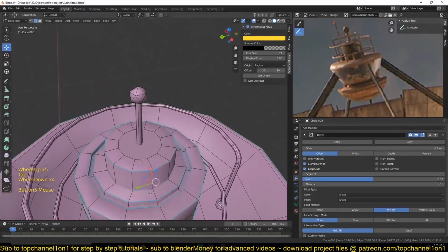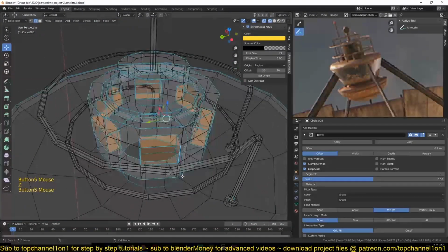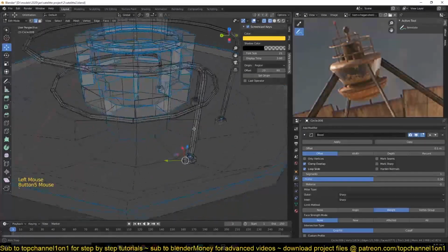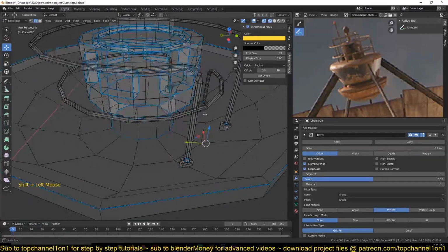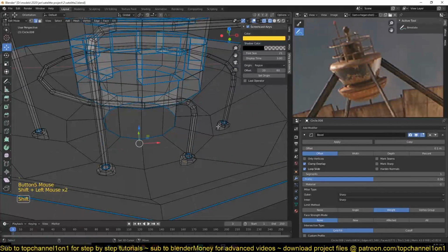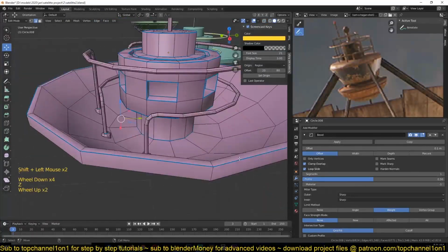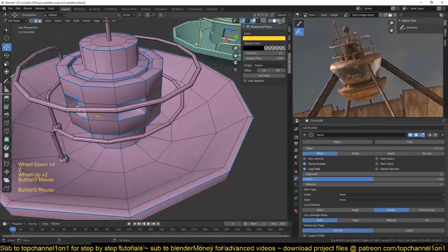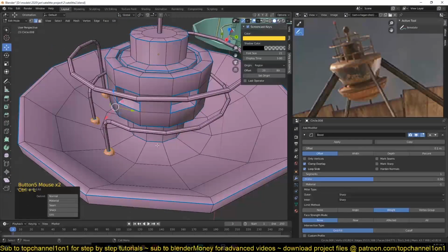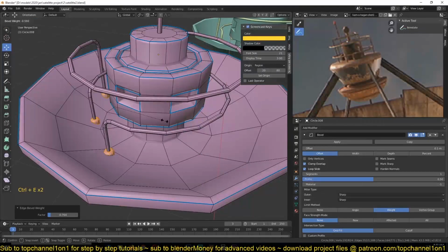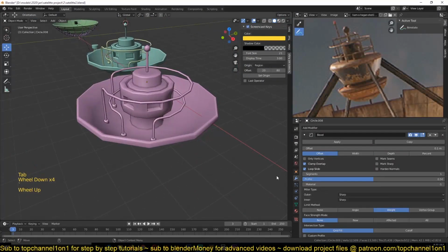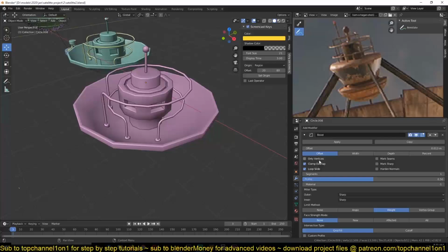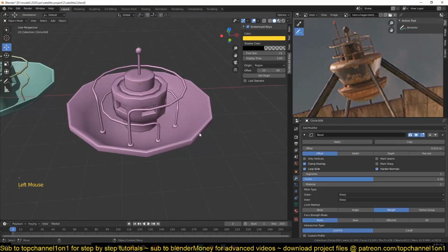Except it seems that we have some elements that, okay, so these shouldn't have any bevel to them. You can see they're affecting how much bevel width we are getting. So let's Ctrl L, select them, and then Ctrl E, bevel weight, and reduce their bevel weight. You can see how the bevel has changed. Hidden normals, and we have that.